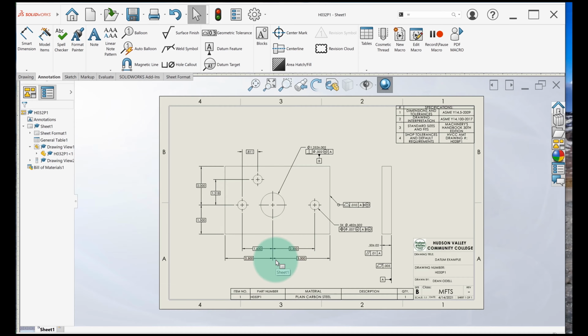What this means is that when we sketch, we can't just choose this bottom left corner as the origin in our drawing. And if you notice, this part isn't symmetric. So it's 2.5 inches here and 3 inches here. We also can't use a center rectangle. So I'm going to show you how to use a corner rectangle and some tricks to get this sketched right. All of these dimensions shown on the drawing become driving dimensions, which means you can change them from the drawing.